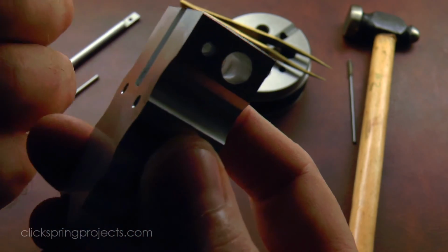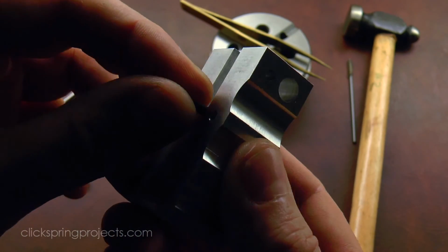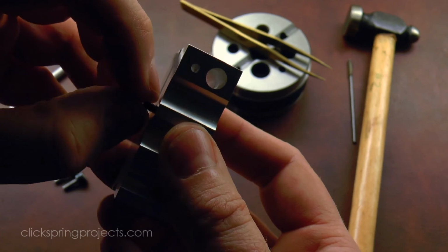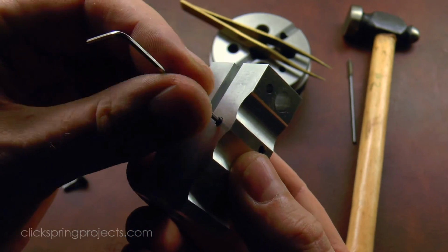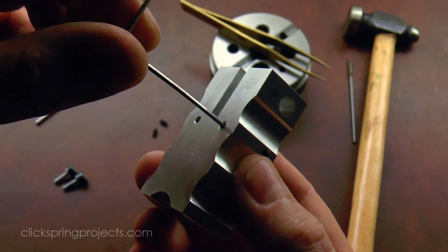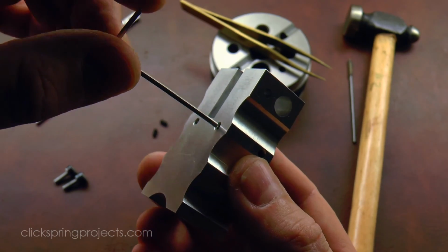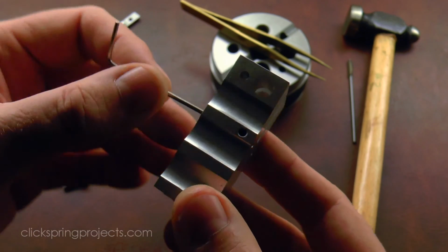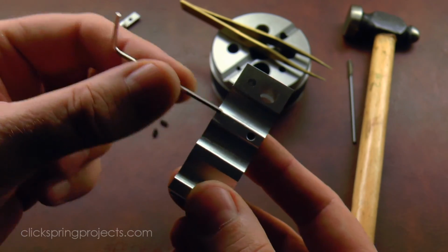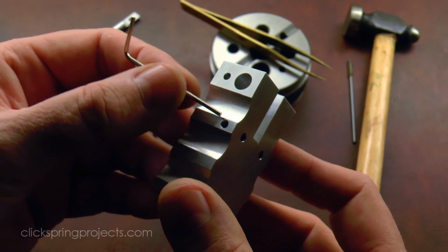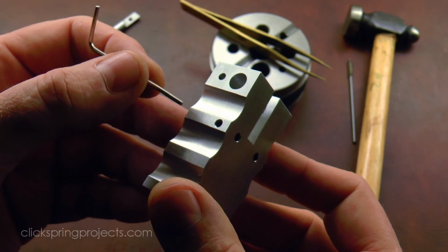One pair of the screws goes in at the sides and so acts to lock the button cutters from moving when inserted in the carrier. The other pair of screws insert into the underside threaded holes and perform the role of a simple jack. They can be screwed in to a high degree of accuracy to advance the button cutter faces to a specific height relative to the tool. Once in the correct position, the side screws lock them off.